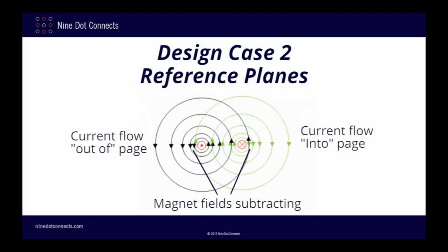And it is the mutual inductance effect that is the dominant factor causing return currents to mirror the trace. When two currents are flowing near each other but in the opposite direction, their magnetic field lines are also rotating in the opposite direction, and thus the overlapping fields subtract. This subtraction causes the effective inductance of each trace to be lower.